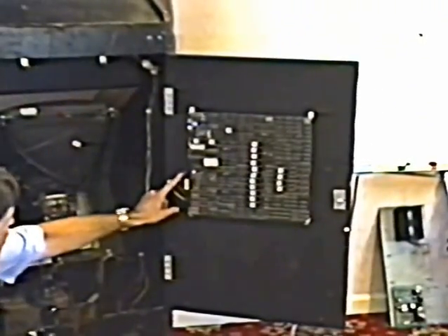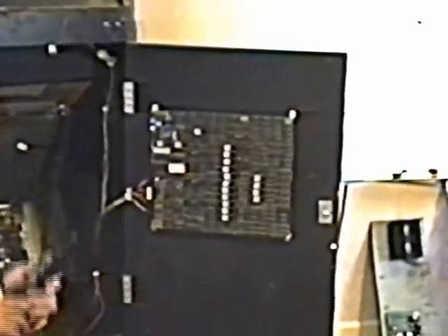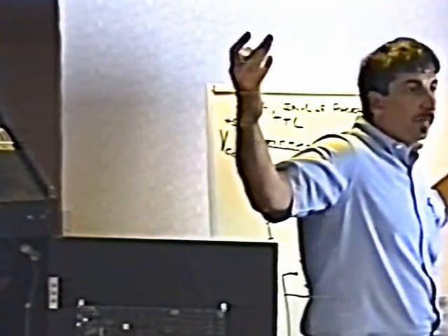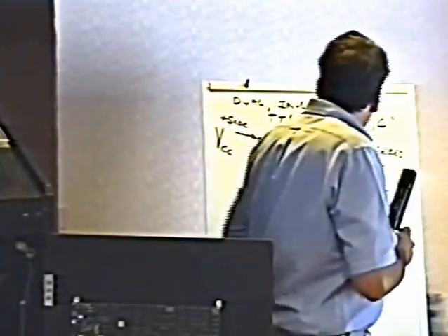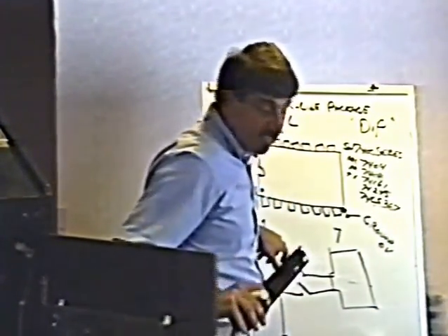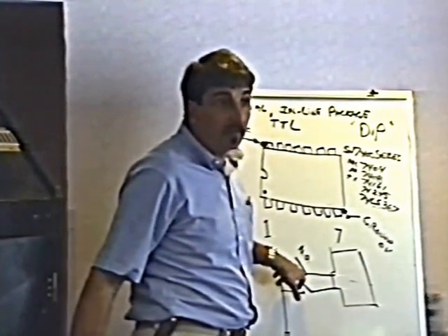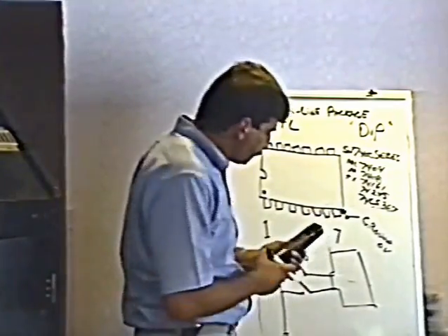If you look at the game, from here the wire goes all the way down here, way up and underneath, and up to the control panel. So the wire is probably a meter long. And it is unterminated. That is, it's sitting there just in the air, basically. It acts like an antenna. It acts like a big, long antenna.